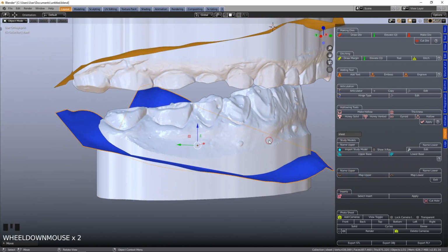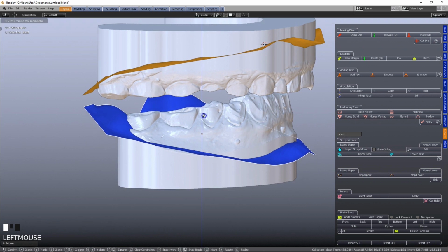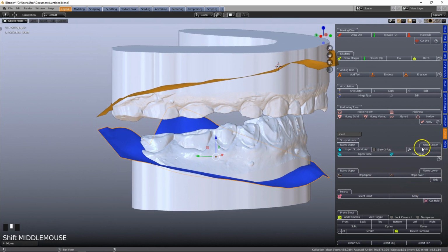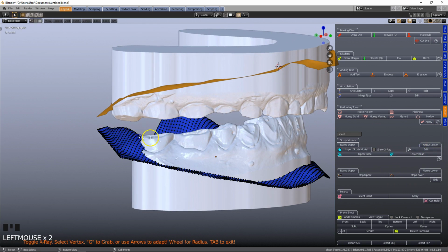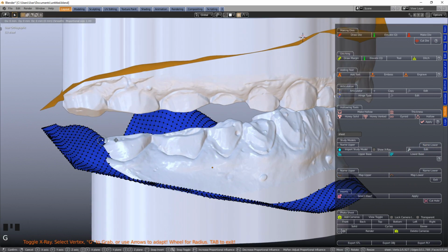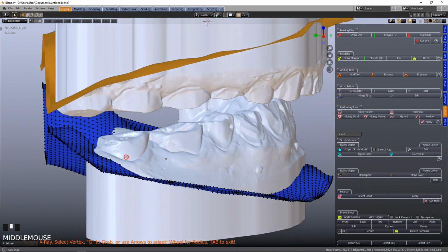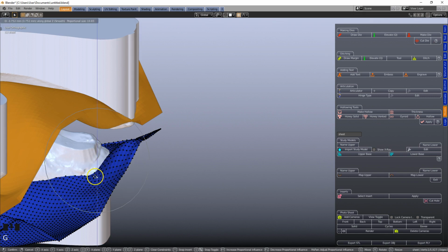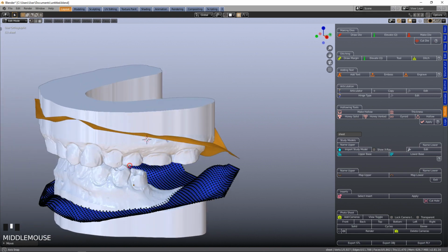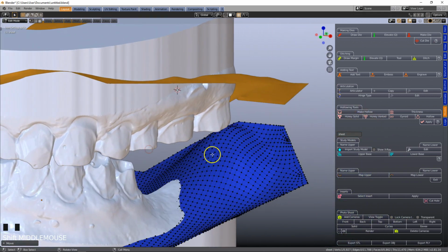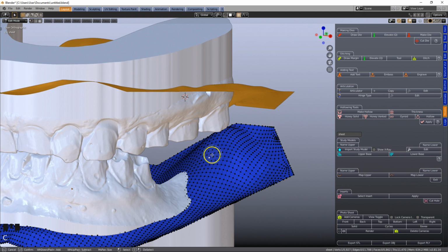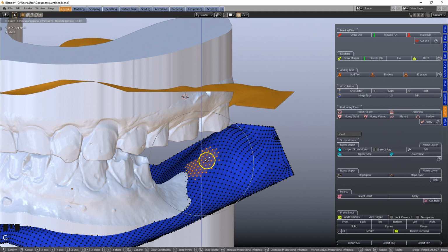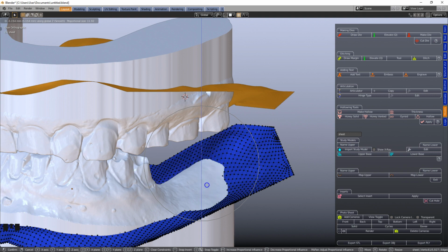If you don't want to shift it down, you can edit it, and that's easy done by clicking on edit, left click on one of these verts, G in the mouse wheel. We can change the effect of the movement, and we can then move it down. G, Z, grab in the Z direction. You can highlight the section, G, Z and just grab it down.